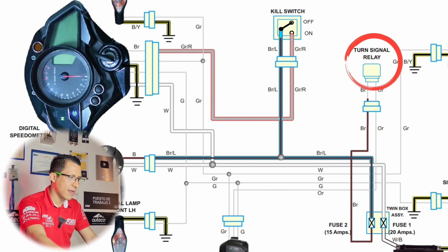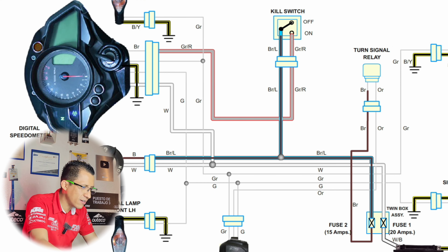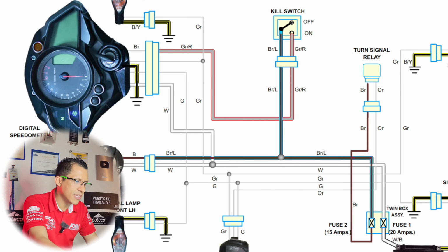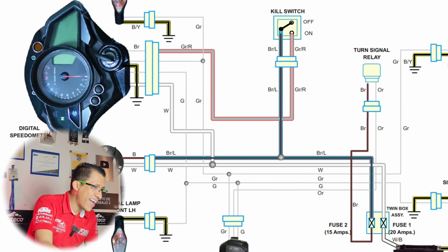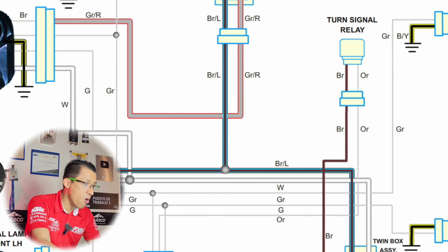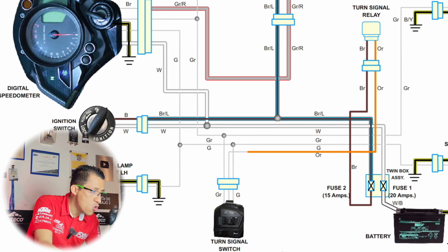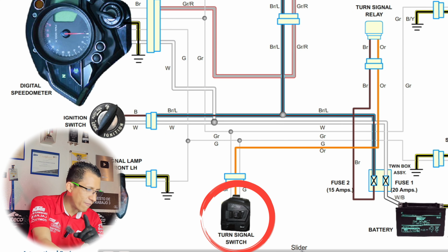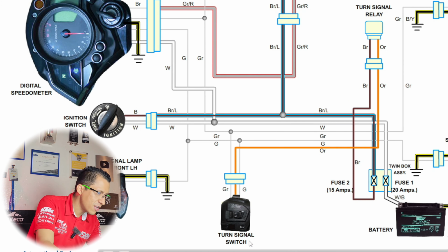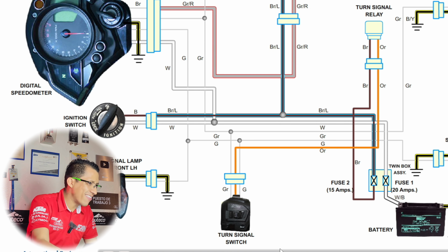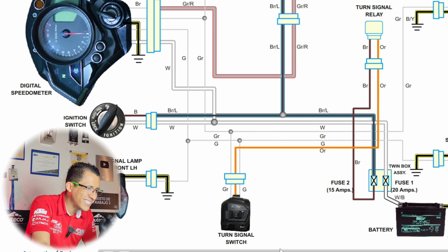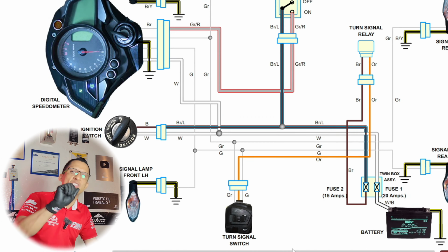It enters the turn signal relay, the flasher, whose function is to receive power, a direct current, and send it intermittently. That is, with a few times it is a flash. See that it comes out through an orange wire, OR of orange. From the orange cable, look where it goes: to our left command, the turn signal switch. And at that moment, there is power to all those components with the simple fact of opening the switch.